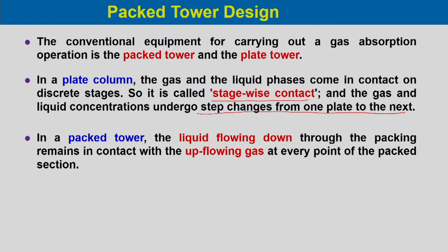Whereas, in case of a packed column, the liquid flowing down through the packing remains in contact with the upflowing gas at every point of the packed section. As you know, in the packed section the packing is placed randomly or in a structured way inside a column. When the liquid flows, it flows onto the surface of the packing material and it is continuous from top to bottom, and the gas also passes through the available space between the packing materials.